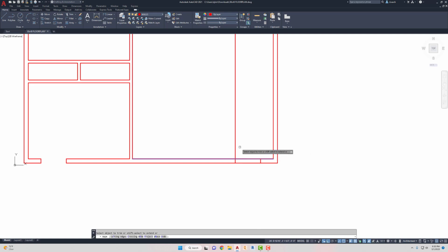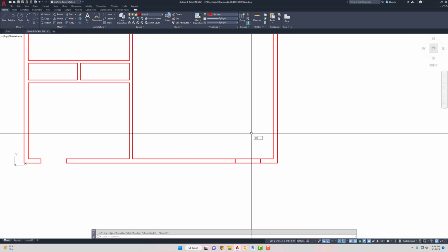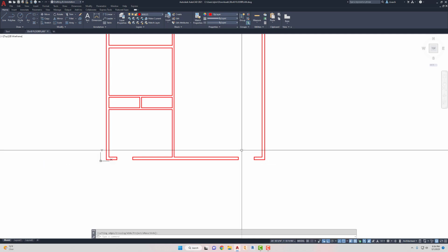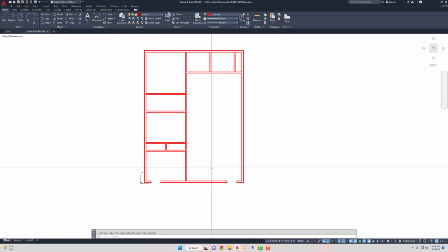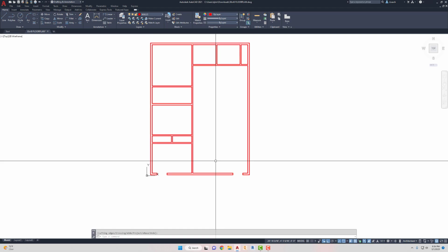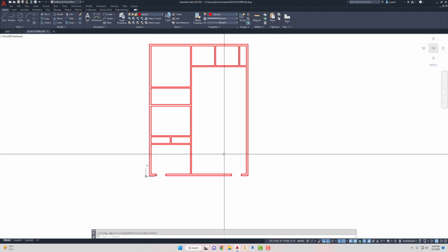And then I can get rid of this and this, and wait, undo that. I need to type in trim again because I used that as a cutting edge, and that wasn't on the cutting edge. All right, so there's those 2 windows. I'll try to make them the same on each side, symmetrical if you're looking at it from the front.